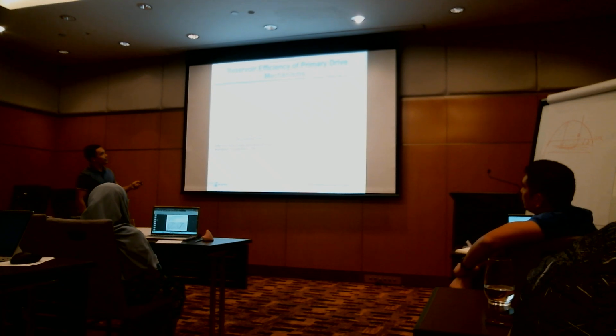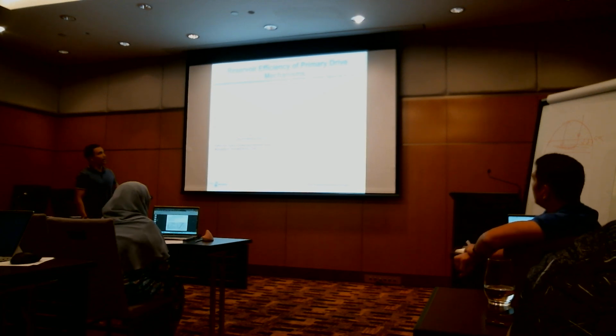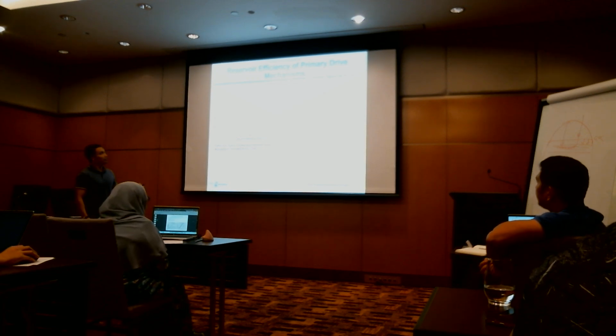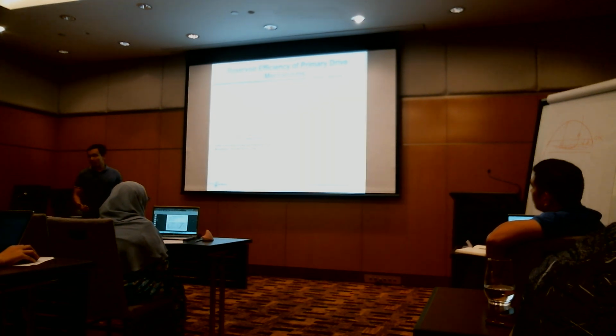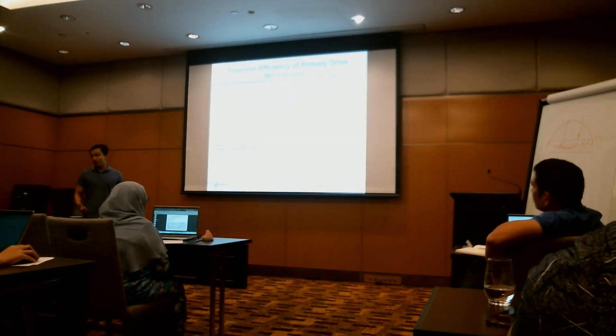This is the reason for low primary oil recovery. It could be due to the reservoir itself, for example a very highly faulted reservoir. The development plan may not be optimized. Perhaps you expected a different drive mechanism, and as you drill you find it's not the best plan that we have. Production facilities, like I mentioned earlier, for gas are highly dependent on the landing pressure.